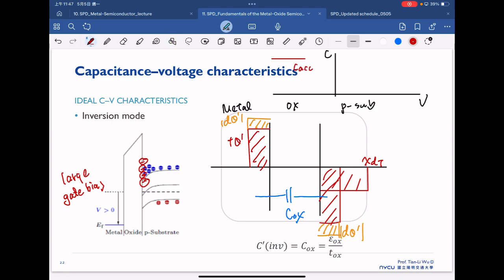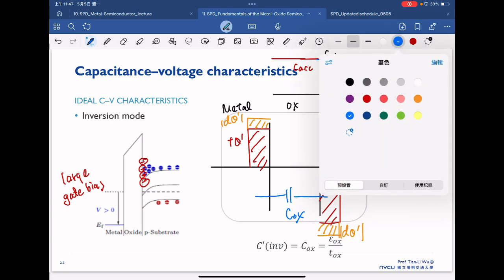And then once we start to gradually increase, this is just for illustration understanding, once we go beyond a certain value, for example the flat band voltage here, we can start to see the capacitance decrease and reach the C min, where this is our depletion capacitance.